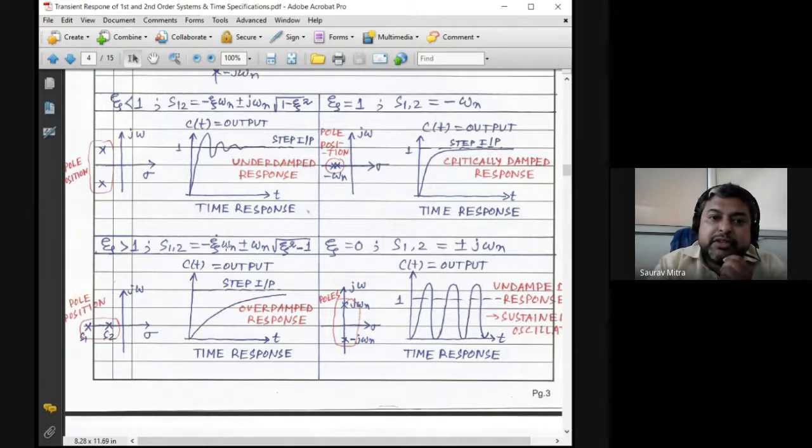It starts from 0, then it undulates up and down, and at a certain point, the settling time TS, 2%, 5%, whatever, it will stabilize at peak amplitude 1. The initial part, where undulations are there, is called transient. Where it is getting stable at 1, this is called steady state. This fourth waveform, the undamped waveform, you should explain first. I will ask you the question, so you can write it down: What are the time specification and amplitude specification of a second order RLC system?